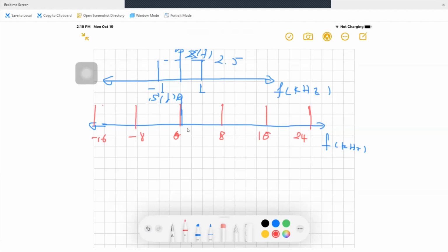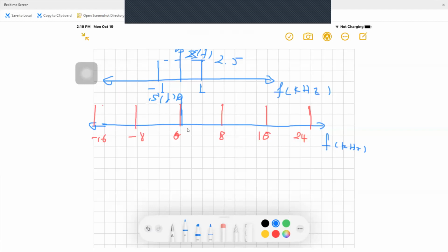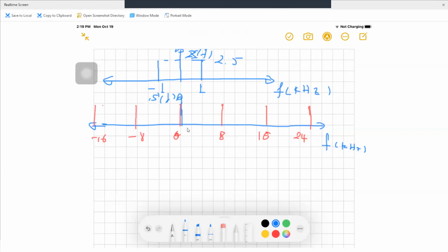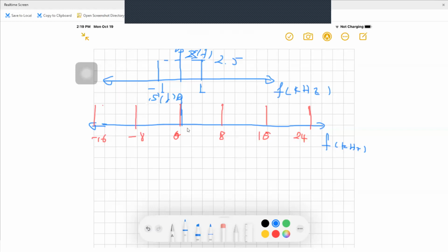This will be the convolution between X(f) and S(f). Teacher, sorry for interrupting, but a simple question: we have fs of 2 kilohertz, and you use 8. Why? According to Nyquist, the Nyquist rate is 2 kilohertz, as I said when we started the example. But in the problem requirement, the sampling frequency is fixed at 8 kilohertz.